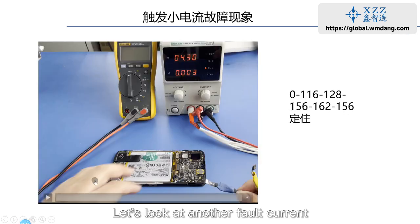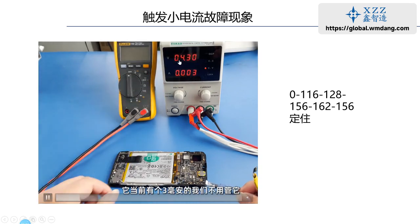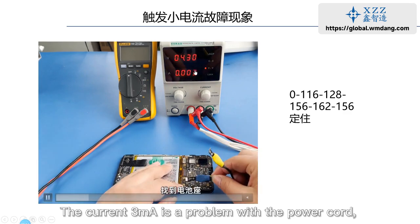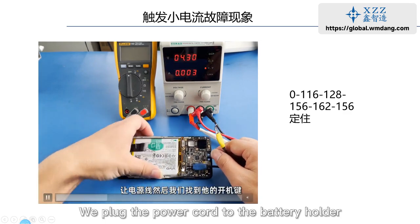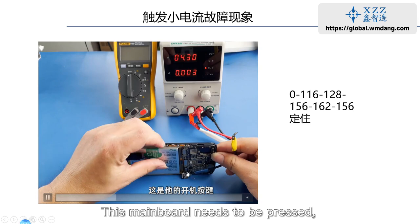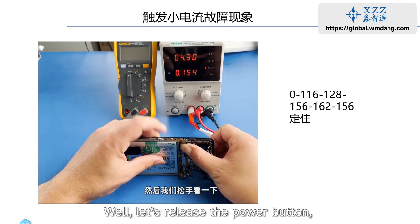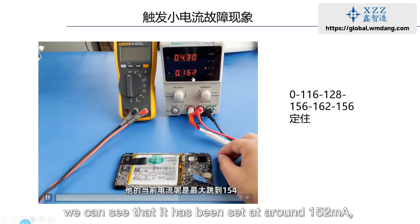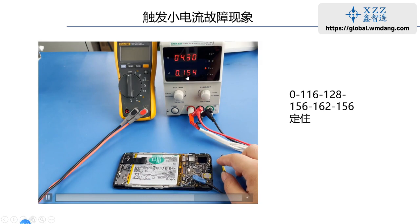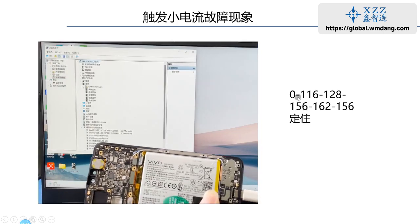Let's look at another fault current. We adjust the voltage of 4.3 volts to the mainboard. The current of 3 milliamperes is a problem with the power cord, so don't worry about it here. We plug the power cord into the battery holder. This mainboard needs to be pressed. We will see the jump of this current after triggering. Well, let's release the power button. We can see that it has been set at around 152 milliamperes and finally settled at 156 milliamperes.